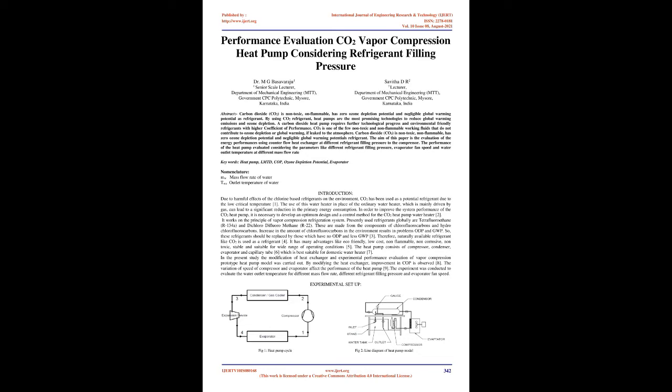The aim of this paper is the evaluation of the energy performance using a counterflow heat exchanger at different refrigerant filling pressures to the compressor. The performance of the heat pump is evaluated considering parameters like different refrigerant filling pressure, evaporator fan speed and water outlet temperature at different mass flow rates. Keywords: heat pump, LMTD, COP, ozone depletion potential, evaporator.